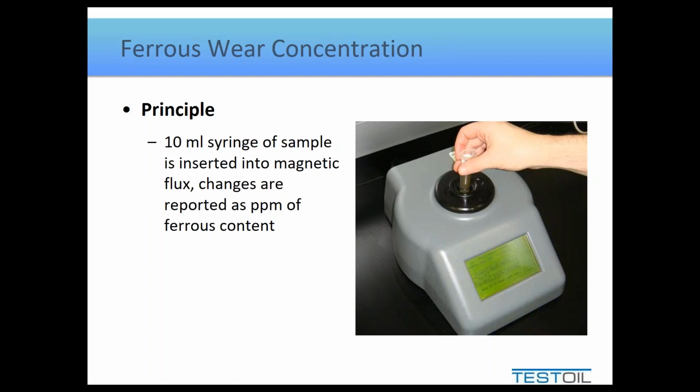Basically, you turn the bottle upside down and let the oil flow to the cap, and it measures the magnetic flux through the cap of the oil sample. So depending on how thick the oil is and how well distributed the particles are, you can vary the results in a PQ index with quite a bit of error.